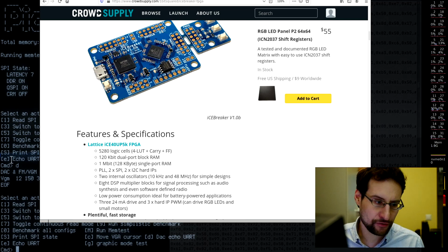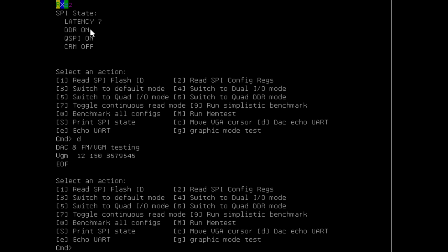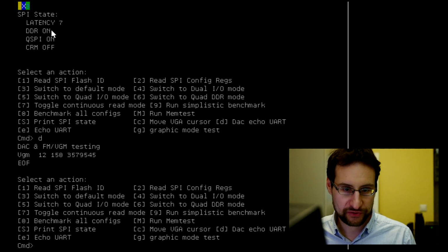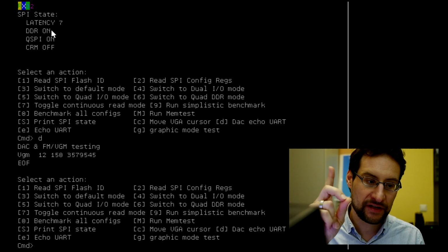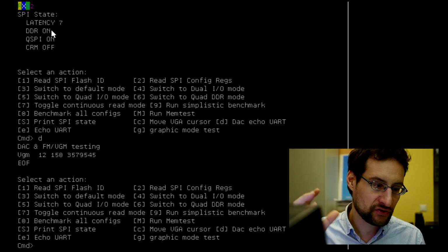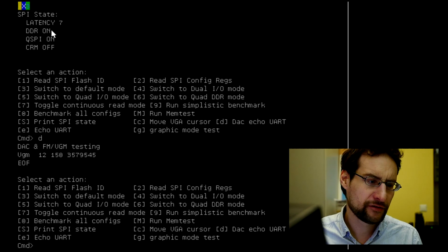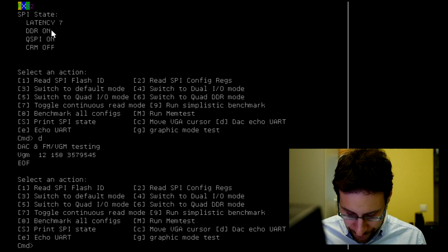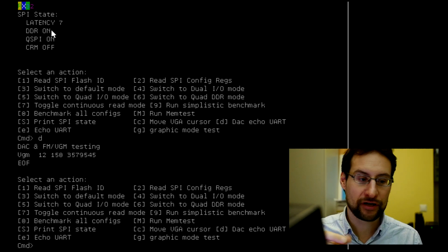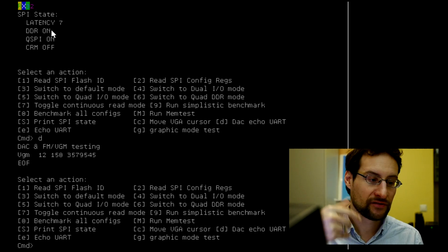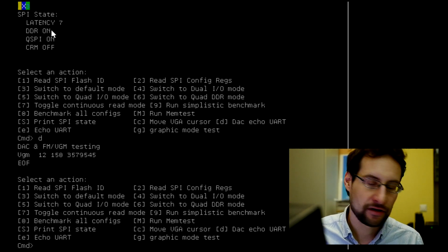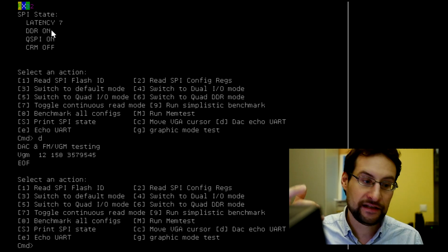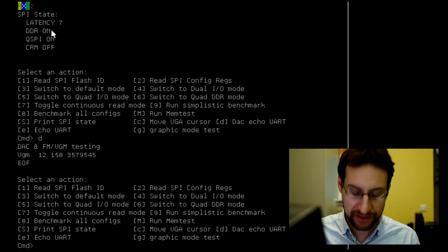Another really nifty thing that I implemented here, which I also need to get used to with these camera views again, is also graphic mode. In the previous videos, if you want to get into all those details, I also had pixel data streaming out of there, even with shades of gray, maybe 4-bit gray. But again, we don't have that much memory. So I opted for now for 1-bit black and white, or actually 1-bit the first and the last color of the palette. So you could change this, you could make this black and green or blue and yellow or whatever you wanted. And to have at least a somewhat decent resolution of 320 by 240,